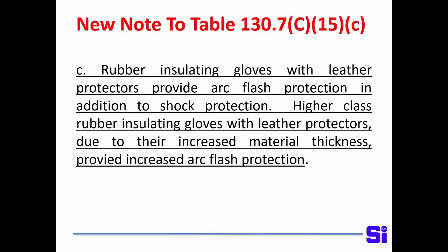If you want shock protection, you have to wear rubber insulated gloves with leather protectors. Now, the good news: W.H. Salisbury did a study where they arc flash tested rubber insulating gloves and leather protectors. And what they found is that they had extremely high values of protection from the thermal effects.